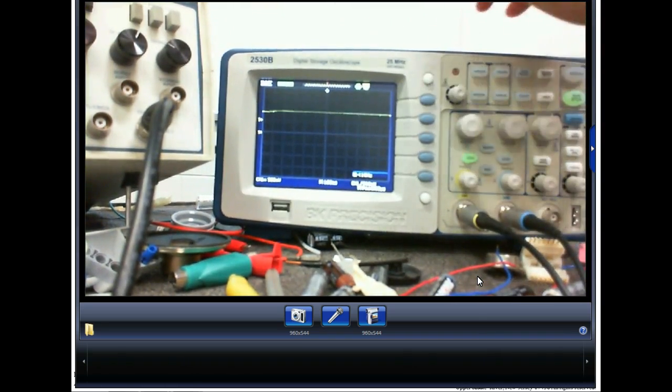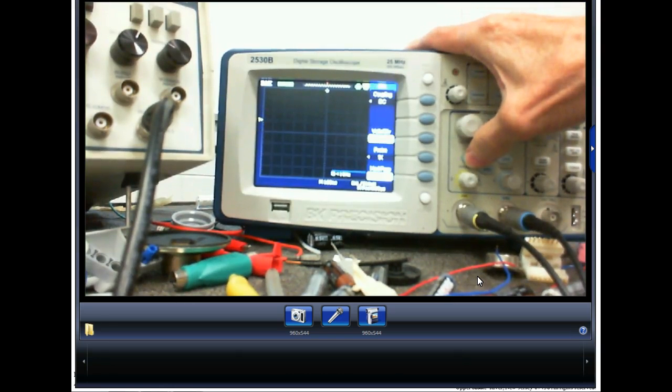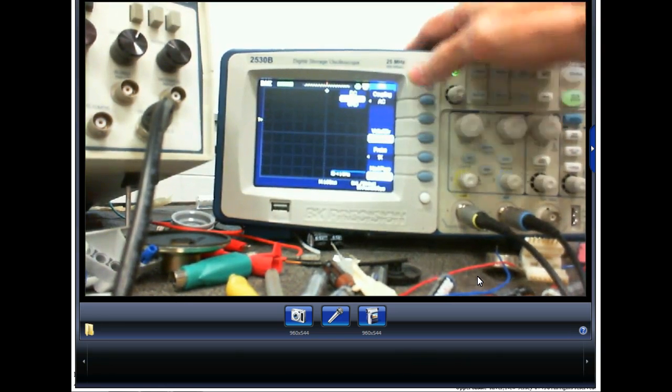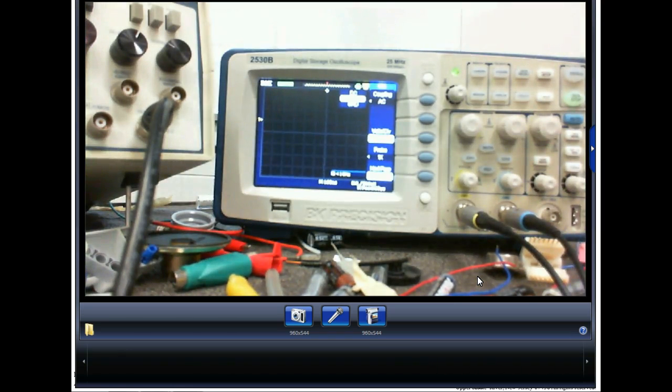So this is where we use this AC on the oscilloscope. We use this to block DC. So when you have it on the AC setting on the scope, it blocks DC. Any other time, we're going to use the direct couple. That's what gets people confused because it says DC. If I measure DC on my meter, by George, I better put my meter on DC. And if I measure AC voltage, I better put my meter on AC. On an oscilloscope, we leave it on DC 90% of the time. The only time we use AC is if we want to do what? Block DC. So I put it on AC.